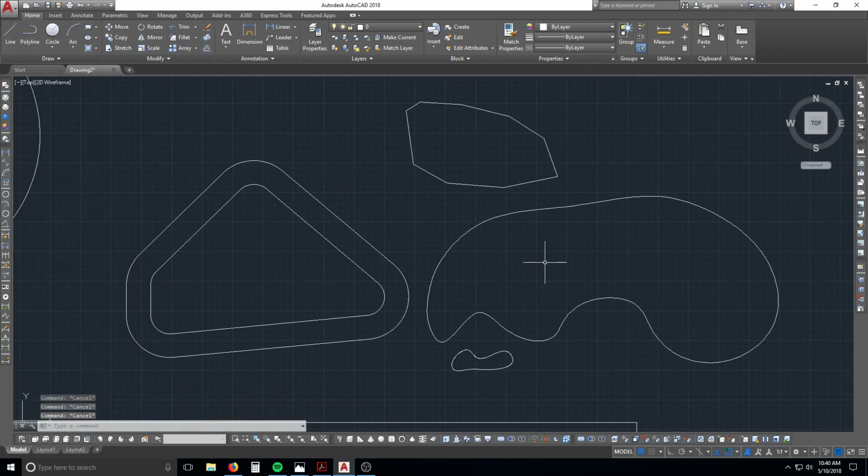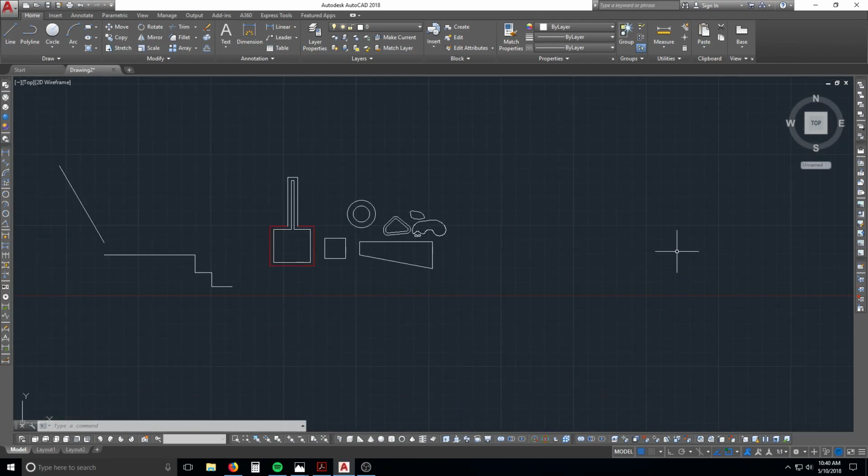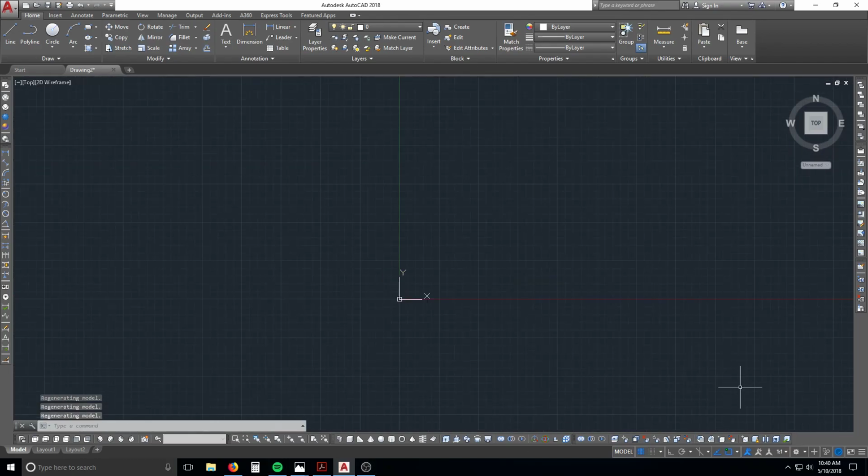So you can think of it in terms of if it was a solid surface and you had poured liquid in it, would it leak? If the answer to that is yes, then it won't work. Because what it's trying to do is calculate the entire infinite, because this drawing space doesn't end.